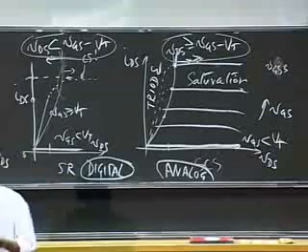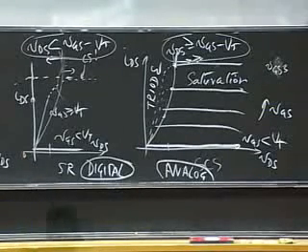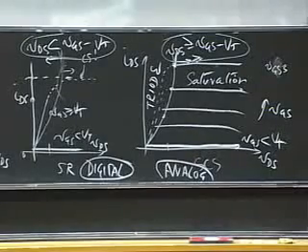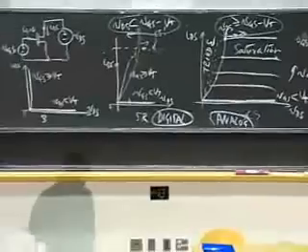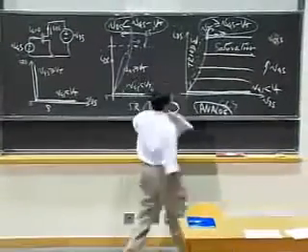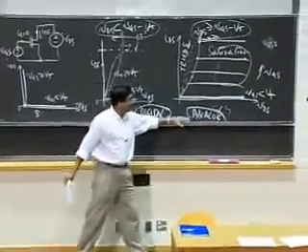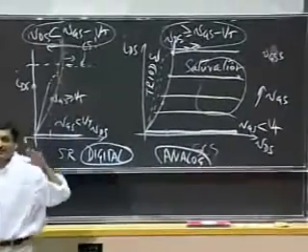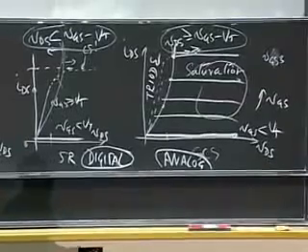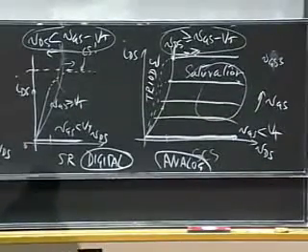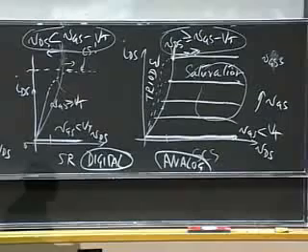We are going to constrain ourselves to play in only this region of the playground where VDS is quite large. Why? Because I'm asking you to. Let's play in that part of the playground and keep your VDS high, and so the MOSFET is going to be operating somewhere in here. So we can apply just the SCS model, just the current source behavior in that region. There's another important reason which I'll get to in a second.